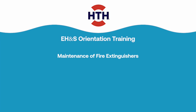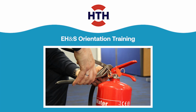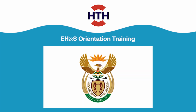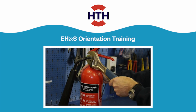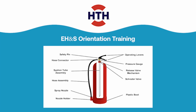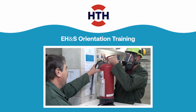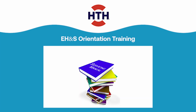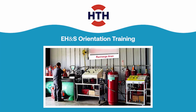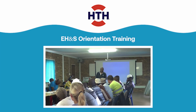Maintenance of fire extinguishers. In addition, fire extinguishers must be maintained annually in accordance with local, state, and national codes and regulations. This is a thorough examination of the fire extinguisher's mechanical parts, fire extinguishing agent, and the expellant gas. Your fire equipment professional is the ideal person to perform the annual maintenance because they have the appropriate servicing manuals, tools, recharge materials, parts, lubricants, and the necessary training and experience.